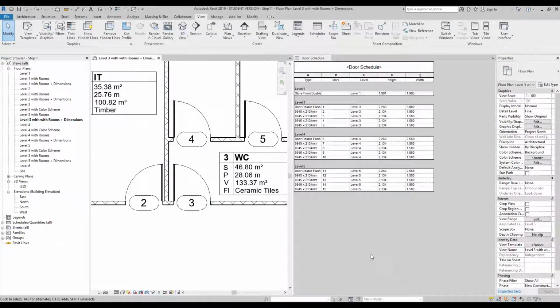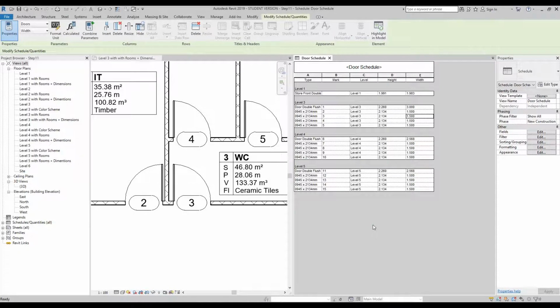Clicking back in our door schedule window, if we were to select door number 3 under the type, under category A, go to number 3, and then once you click it, you get a pull down menu. Now let's just change this to 0813. Once you do that, you will notice that our door in our plan and in our model automatically updates.